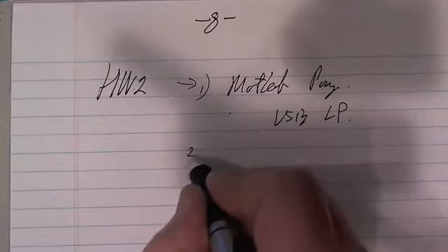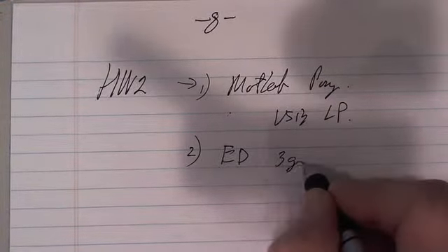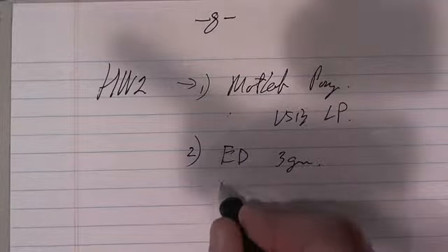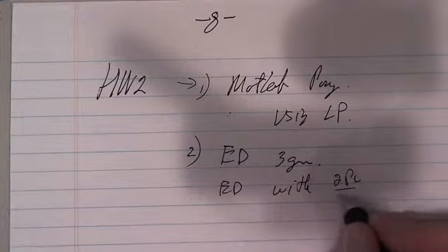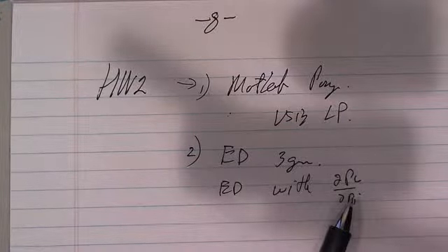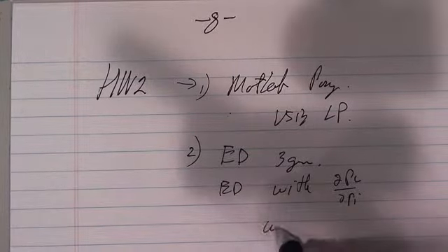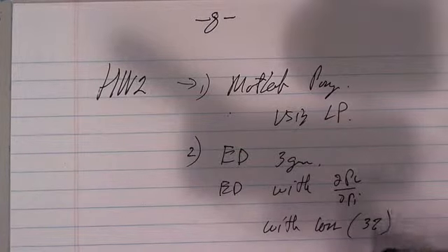Problem 2 is you're going to do an economic dispatch on 3 generators, and then an economic dispatch with loss. You're just going to do it once; you're not going to try to come back and recalculate. We didn't show you how to do that, so we'll assume the loss factors are constant. With loss, which I think was 3%, I said make it equal to 3.